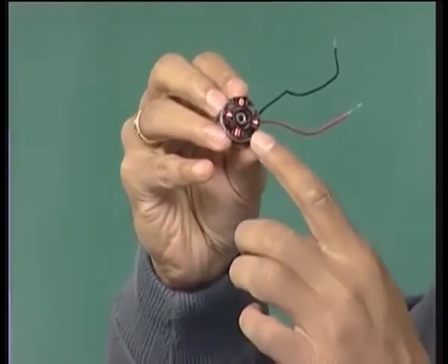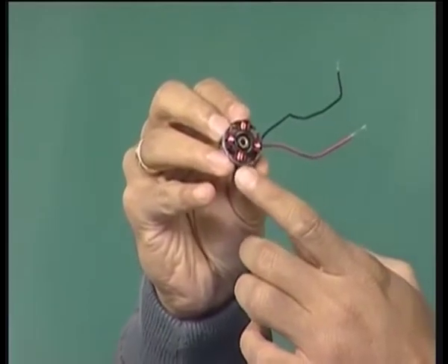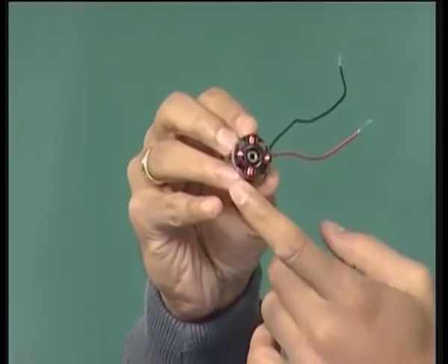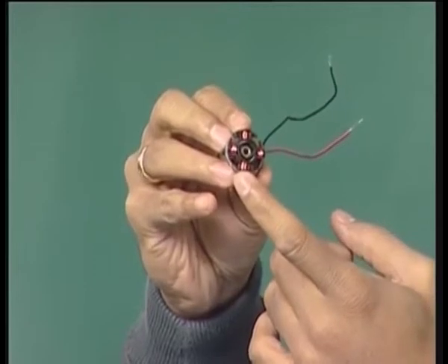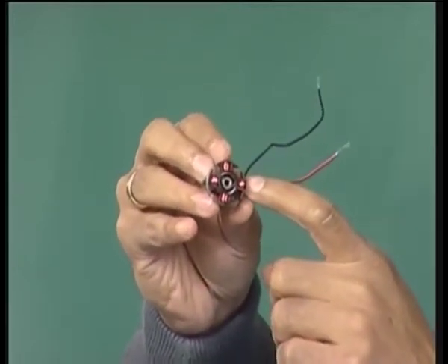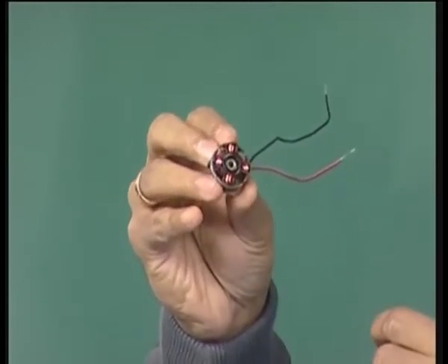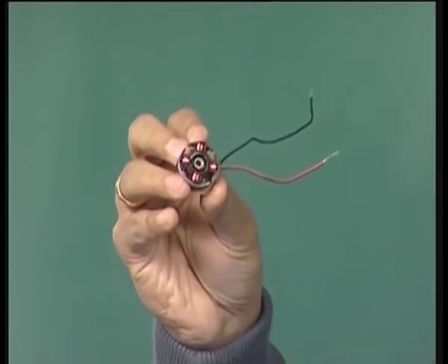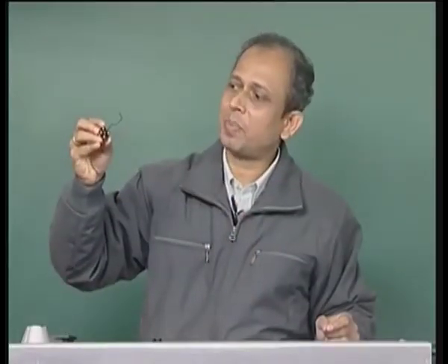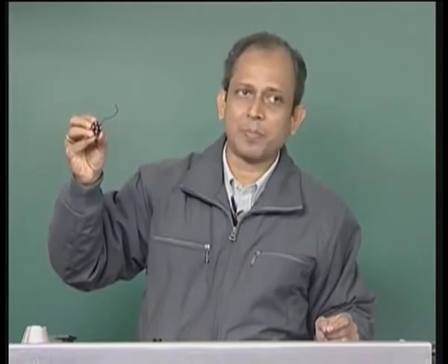So the stator is excited. As you have seen that we have a photoencoder, similarly, the rotor position is sensed, and these windings are excited, maybe W1, W2, W3 and W4. And since we have 4 windings, we must be having 4 transistors. Each winding is excited by a single transistor. So in this case, we are expecting that these windings should be connected to at least 1 transistor.